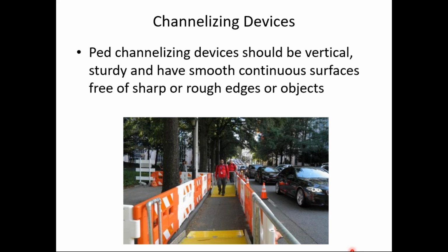Probably has dual left turn lanes, maybe right turn lanes, through lanes, probably has a median in the center with the big mall sign, probably is traffic signal controlled. That's a private driveway, but that looks and acts like a street. So I would put detectable warnings where the sidewalk crosses that street.